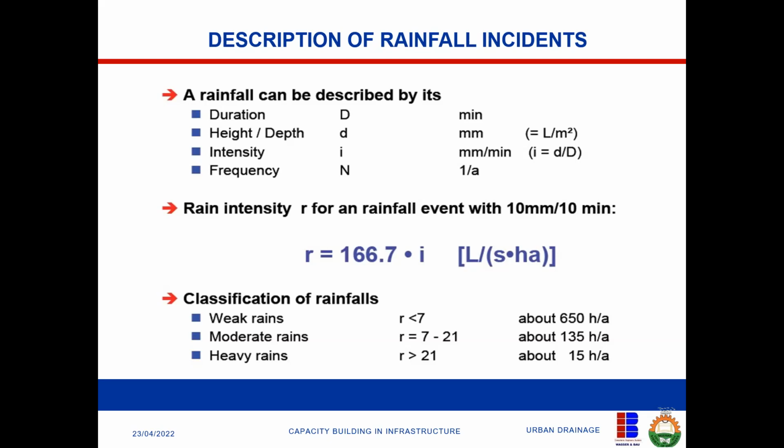You can get these values through modeling. Now, if I say I'm using 10 years as my design period, the frequency is 1 over 10. And 1 over 10 is 0.1. So the frequency or the probability of that rain occurring is just 0.1.